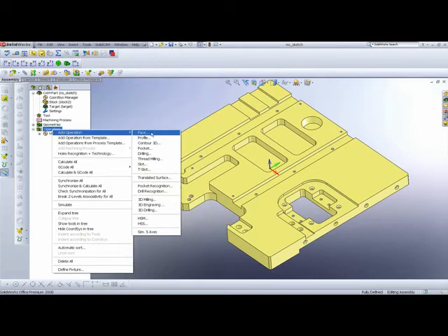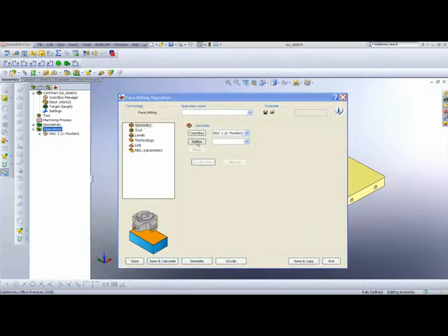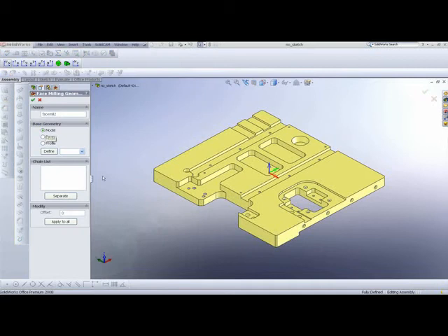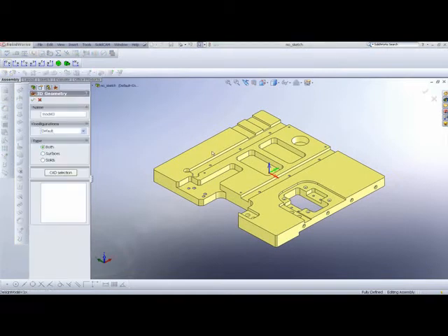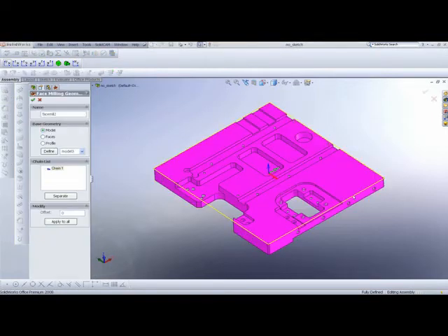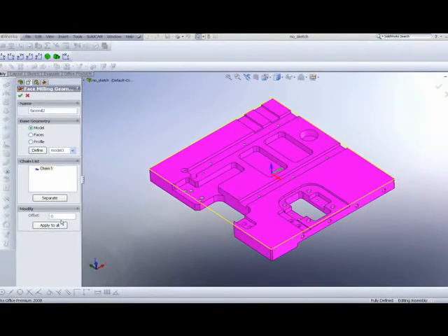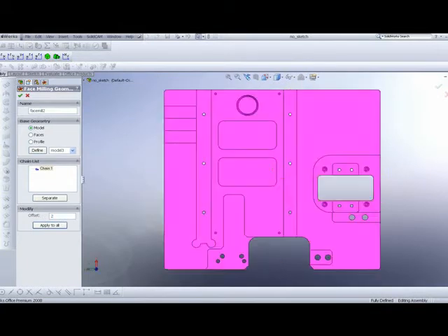What I'm going to show is a face milling. The purpose of this operation is to clean a flat area without the need of using a sketch at all. In the define geometry, we select the model, define, click on the entire model, and automatically we get a boundary surrounding the part, and we can use the offset field here to enlarge the offset. We can look from the XY plane.